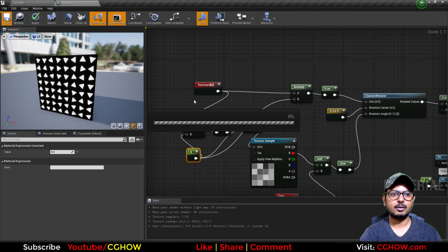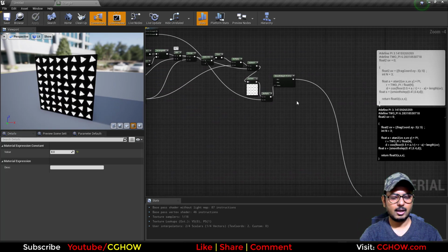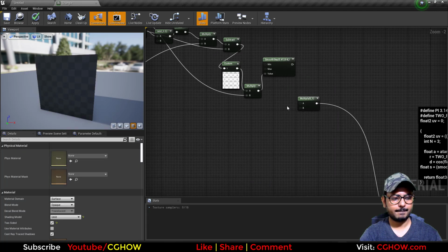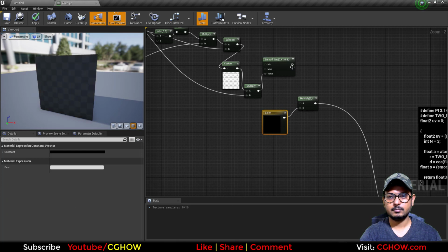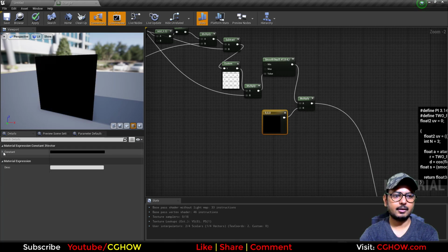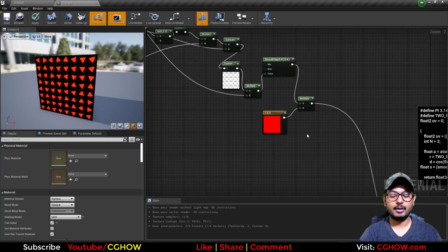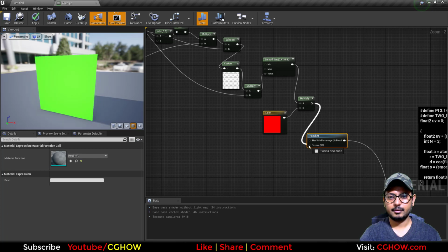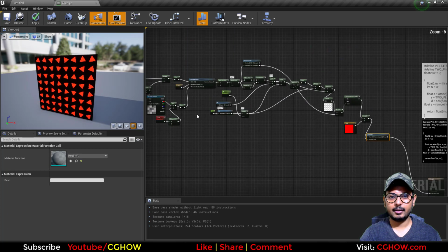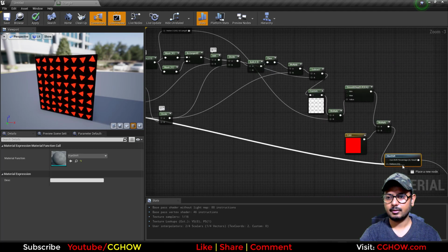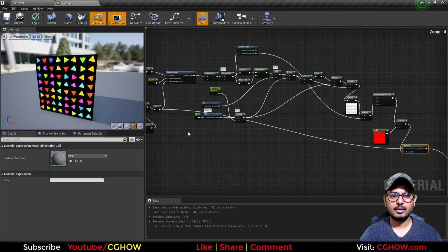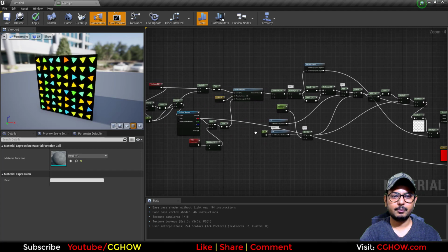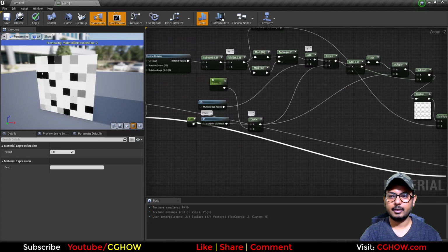And you can also randomly colorize it. So let's say I multiply it with color. Let me put it here, 3, and I take the red color. So these are all red. So if I take the hue, and in the hue value, I again can take this thing, randomize color. If you take this, it will just randomize color once. It's not animating, but this value is animating. I can use this here.